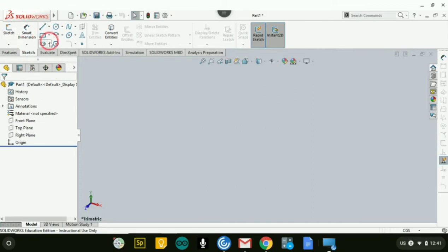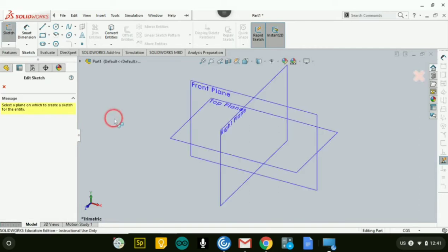Now our Sketch tab has all the tools necessary to create a sketch of a 2D model or drawing. And the idea is that from that 2D model or drawing that you create, we're going to be able to make that into a three-dimensional model. So to begin, we're going to want to click on our sketch function, which is up in the top left corner. Go ahead and click down.